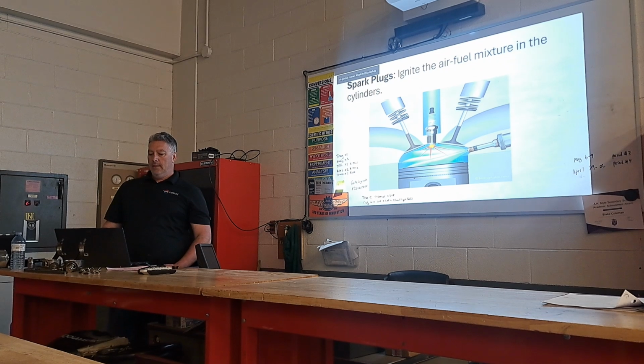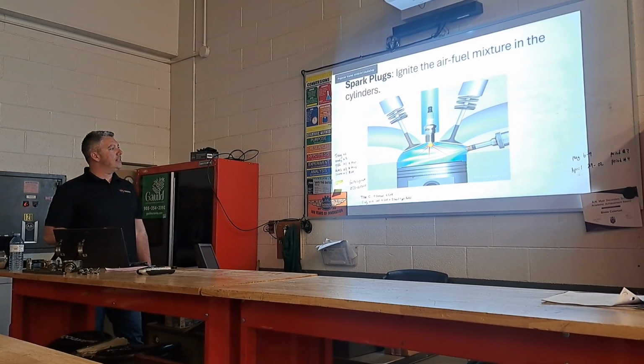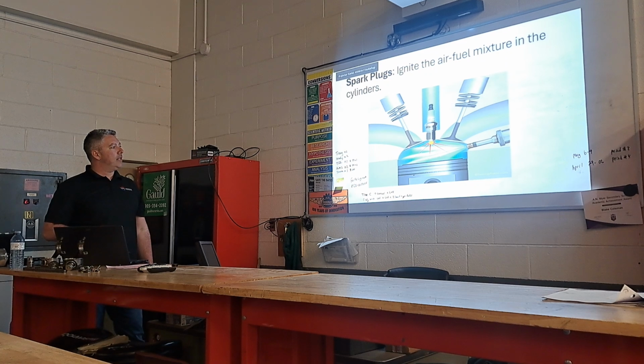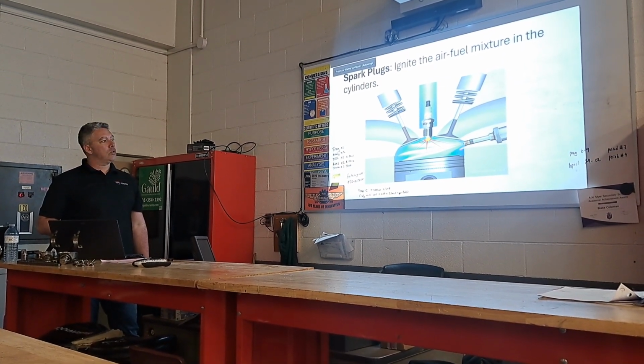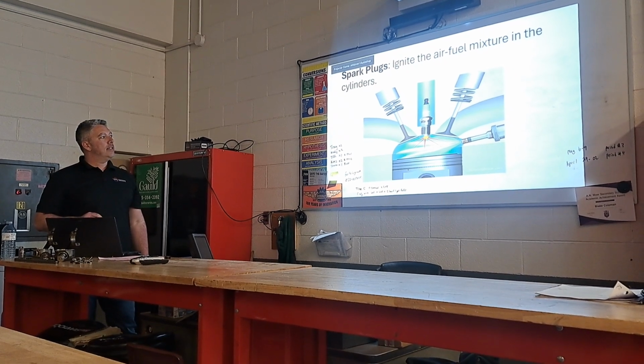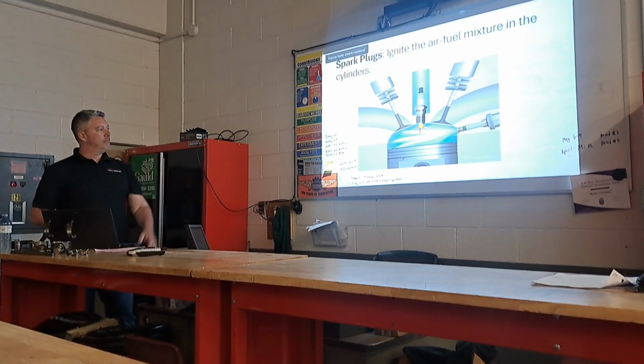Spark plugs. They ignite the air-fuel mixture in the cylinder. So, the intake valve will open, letting air come in. Same time, the computer tells the fuel injector to squirt some fuel in there. Then the spark plug ignites, causing a combustion. Boom.